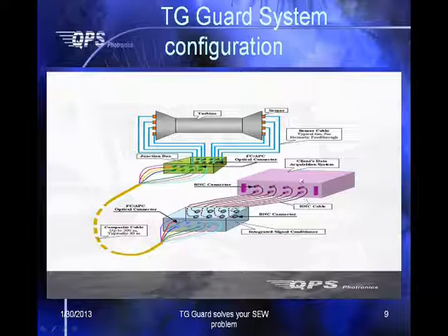Competitive products usually have to do the optical to electrical conversion right away on the cover. The unfortunate thing is that after conversion, the electrical signal is conducted by a long electrical cable, which acts like an antenna.